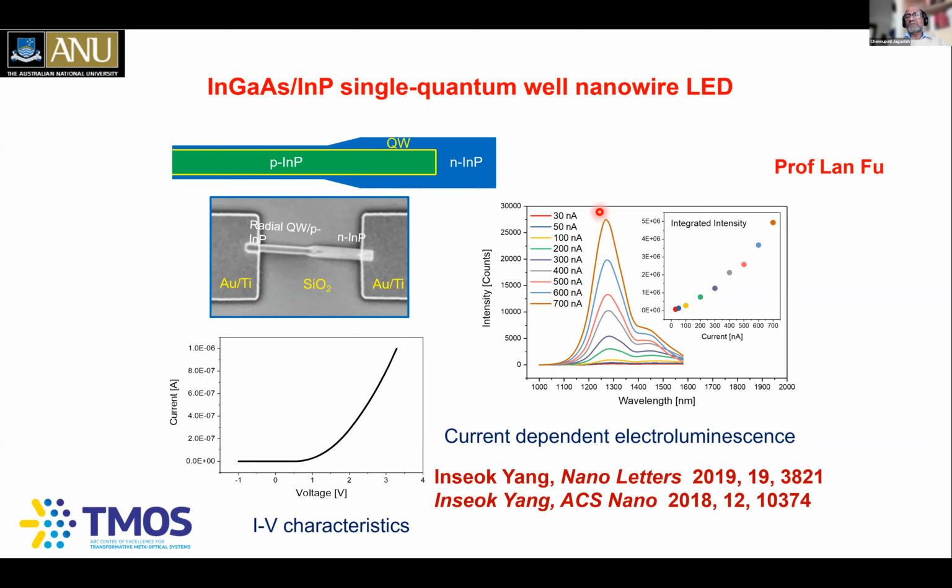That's what you typically expect from a laser. You also don't see any threshold-like behavior in light output versus injected current. So this indicates that these devices are acting like nanowire light emitting diodes, with spontaneous emission, but not like a laser with stimulated emission. So you ask the question, why? What is the reason for that? Because you got the nice nanowire, you made the PN junctions, you got the gain medium, so what's the problem?